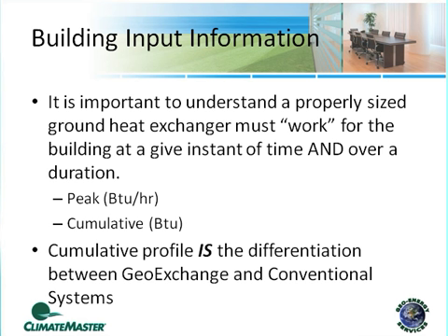If we have a 20,000 square foot building and it's an office building, yeah, it may have a 40-ton peak BTU per hour heating load. But it's an office building. What if I take the same building, the same square footage, and it's still 40 tons of peak BTU per hour, but instead of an office building, I tell you it's a school? Well, that load profile difference is going to affect the cumulative effect of BTUs this thing needs to provide over a given month or a given period of year.